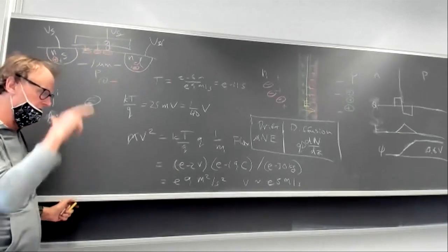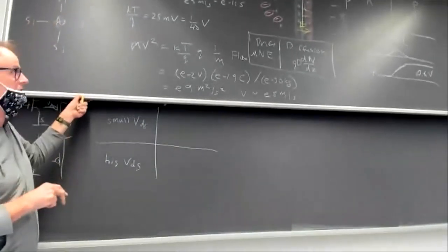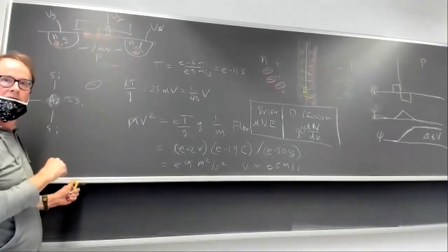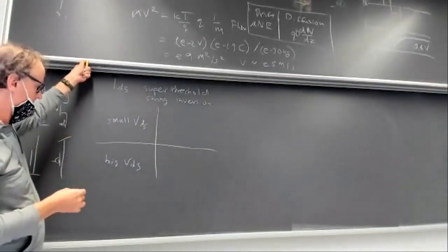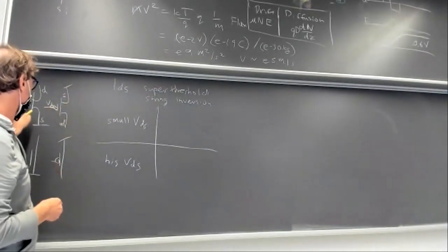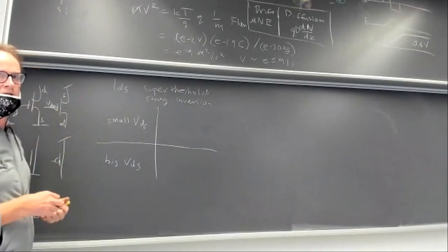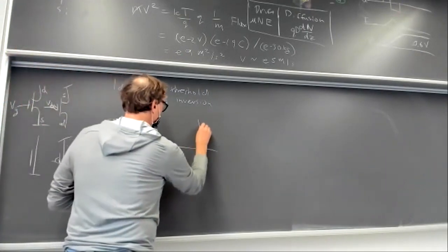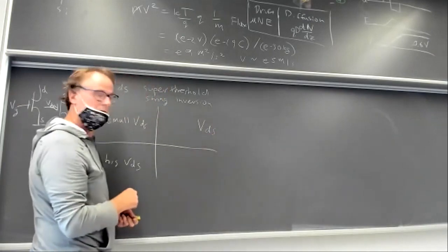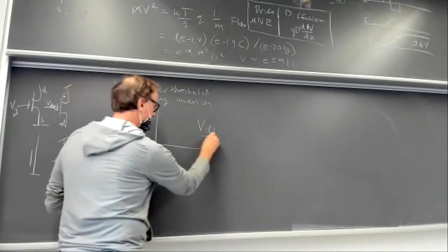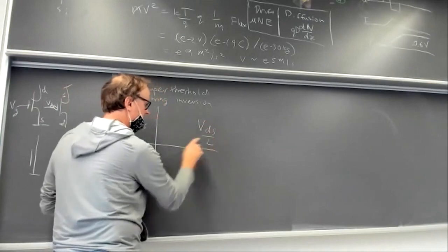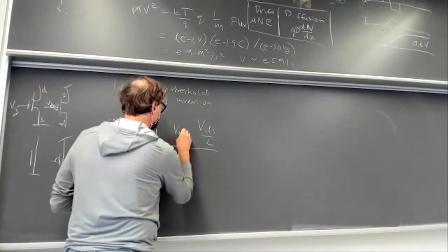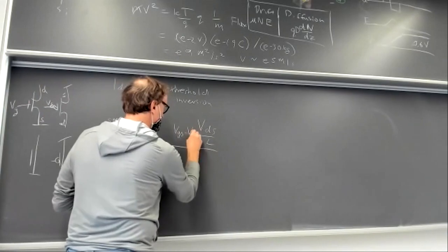It's not a vapor of electrons, it's really a sheet of charge, a macroscopic sheet of charge, which has a higher density than this doping density. That's kind of the threshold amount. At that point, you have a sheet of charge in the channel, which is proportional to the gate voltage minus this threshold voltage. And so then the current flowing in the transistor is proportional to the electric field across the transistor, that's the VDS divided by L, the voltage divided by the length, times the charge density. What's the charge density? It's the gate source voltage minus this magic threshold voltage.